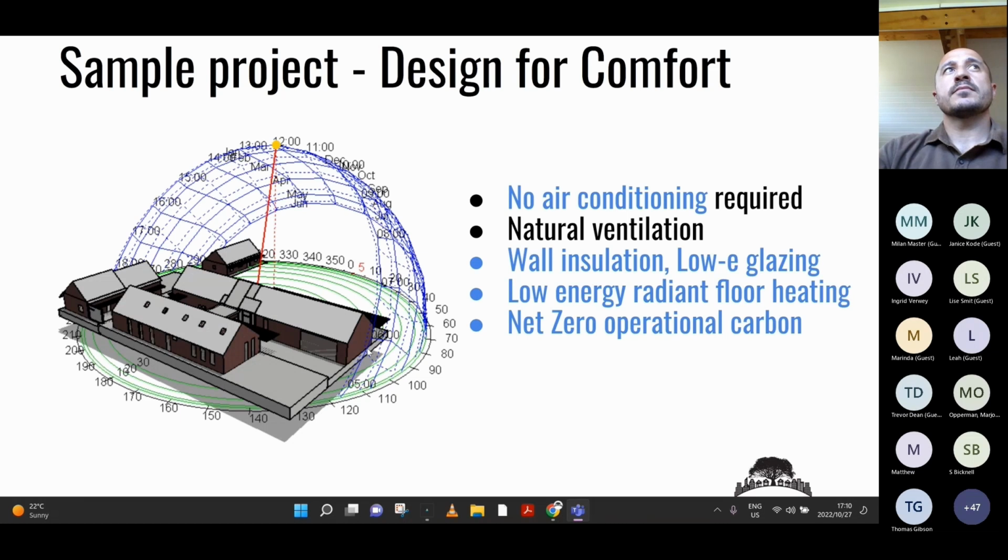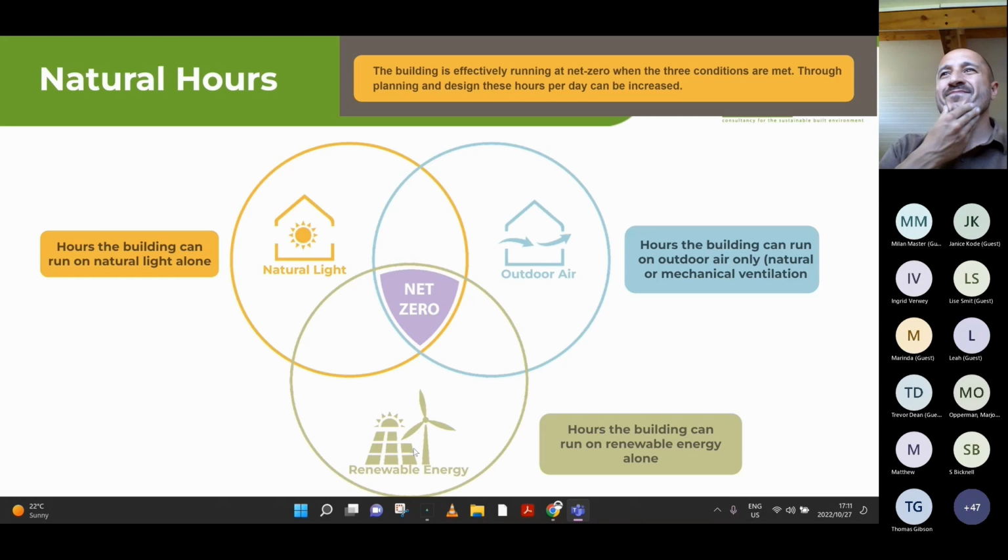And the reason that it is very energy efficient is that you have a constant temperature that you are rejecting heat to. So if the air was 35 degrees, you need a lot of energy to push heat against nature. Energy doesn't flow from cold to hot, so you need more energy to use a system that is using air for heat rejection. But your ground is at a very stable temperature, like a constant 19 or 20. So your effectiveness of cooling is improved because you are rejecting heat to a colder place.